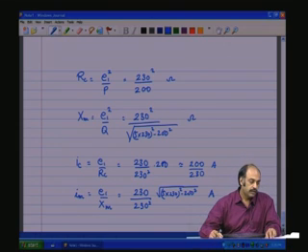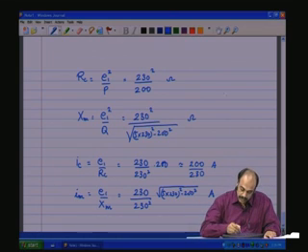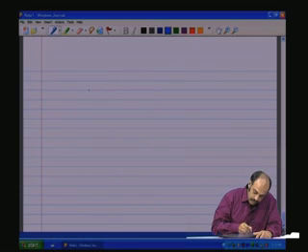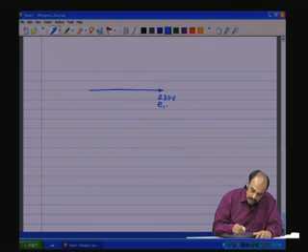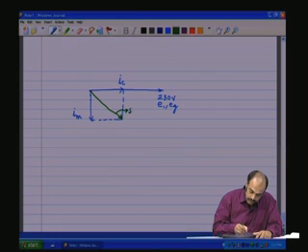and one can plot the phasor diagram and see that if we have 230 volts, this is E1 or EG, we are going to have IC, and there is going to be IM, and the resultant, that is going to be 5 amps.